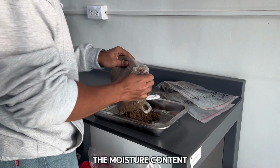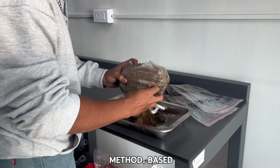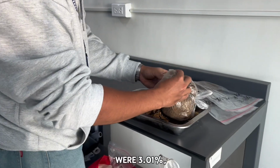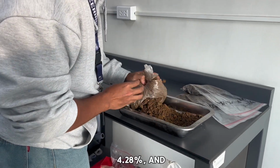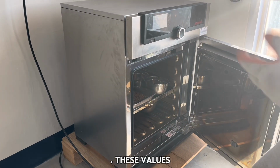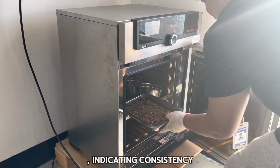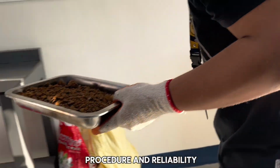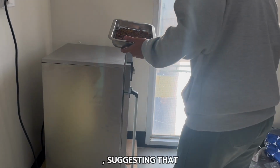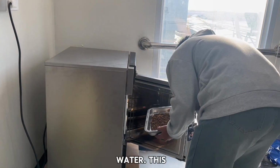The moisture content of the soil sample was determined using the oven drying method. Based on the results, the computed moisture contents for the three samples were 3.01%, 4.28%, and 3.21%, respectively. These values are relatively close to each other, indicating consistency in the testing procedure and reliability of the results. The average moisture content is low, suggesting that the soil sample is relatively dry and contains minimal water.